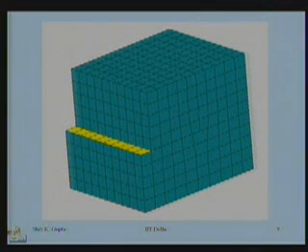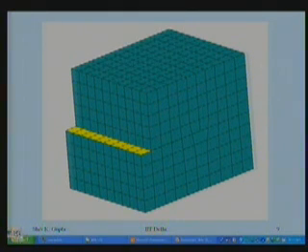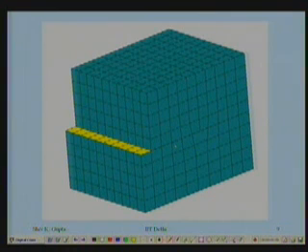Right. Now I have shown a three-dimensional solid crystal, simple cubic again, with the configuration of an edge dislocation. This is that part plane which stops here, and as shown here, is a positive edge dislocation, coming from the top and stopping at the slip plane, which I have shaded yellow here.